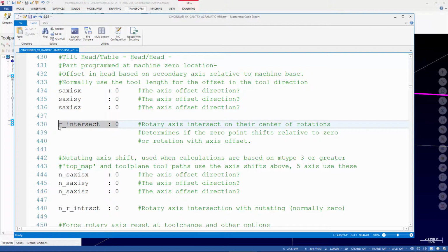Normally we recommend people don't do that, because quite often you're going to end up having to set and maintain the shift values inside the post for every new part. So basically you're going to have one post for each part if those values are changing here. That's why I recommend people set the post up where the center of rotation is your WCS origin, and you build your fixture and part holding as it exists in the real world.